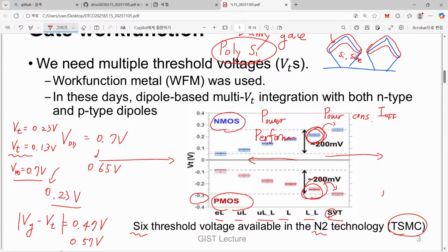For example, we have 6 different devices with different threshold voltage, but since that is used for the standard one, I will make another treatment for this guy. And if we have extremely low threshold voltage, I will do some additional treatment for this one. Usually our technology is so tight that we do not have many other knobs to tweak performance.